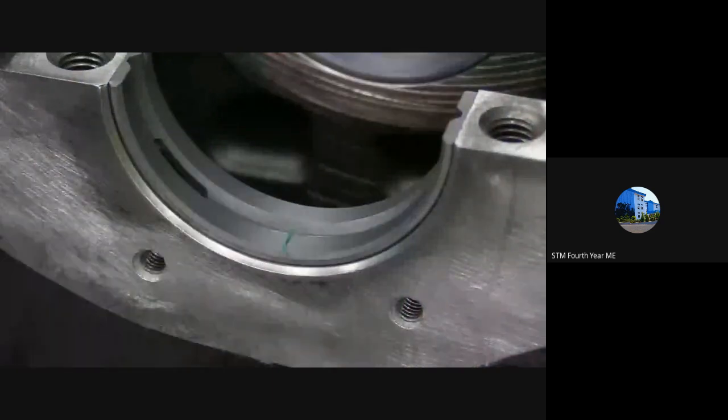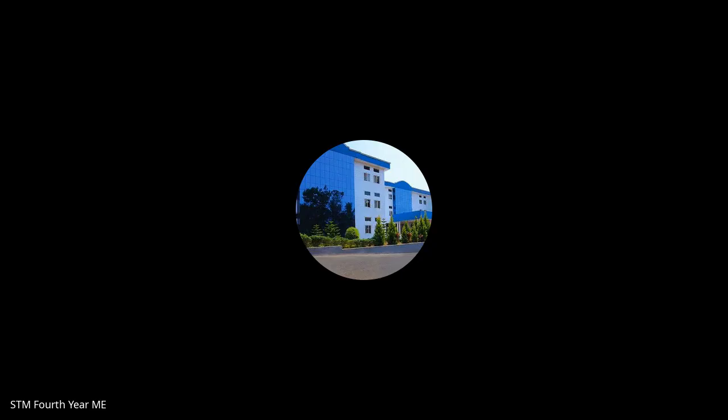Okay, so first lubricating the surface of the bearing by applying lubricating oil, we can add both. And after that, we set the piston and connecting rod, which is clamped. The crank pins and journals are cleaned. Now, on the surface of the bearings, we will place the crankshaft.